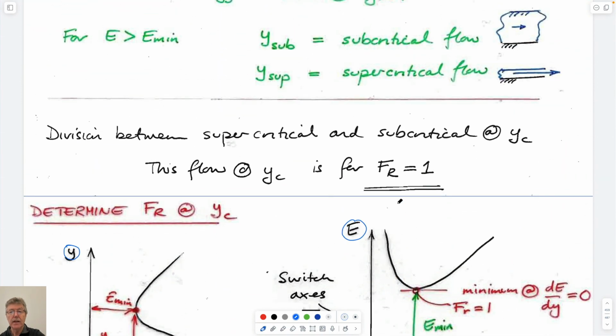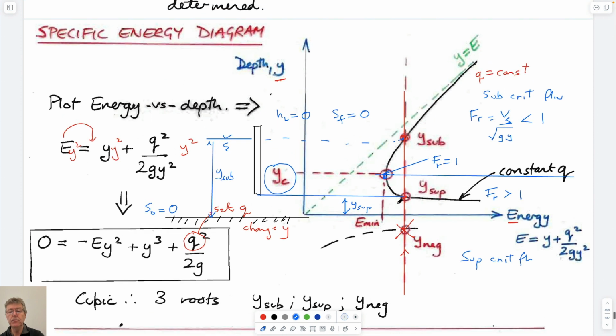And I suppose if you choose a different flow regime, what you don't know is, if you don't have this constriction for flow within your stream, and you know the amount of energy that you have in your system, it could organize itself as either one of these. And so you have to choose which one it would go between. If you want to move from this subcritical flow to the supercritical flow, then the only way you can get there is that you have to be on this curve. This curve represents a constant flow rate.